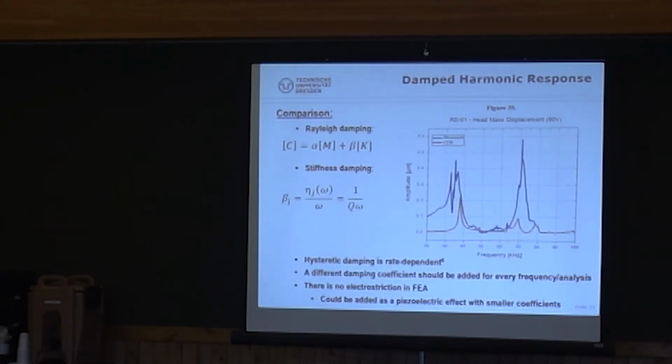Are you able to have that second damping value change at will? And if so, if you decrease the damping, then the second mode is going to get higher and higher? Yeah, that's what I do, because actually I implement the experimental Q factor to determine the damping constant, and then I take the Q factor at the second resonance frequency to get me a second damping coefficient. What I'm saying is, in your model, increase the second Q value to a high enough value in order to have a response similar to the blue. Okay, we'll see what that does.